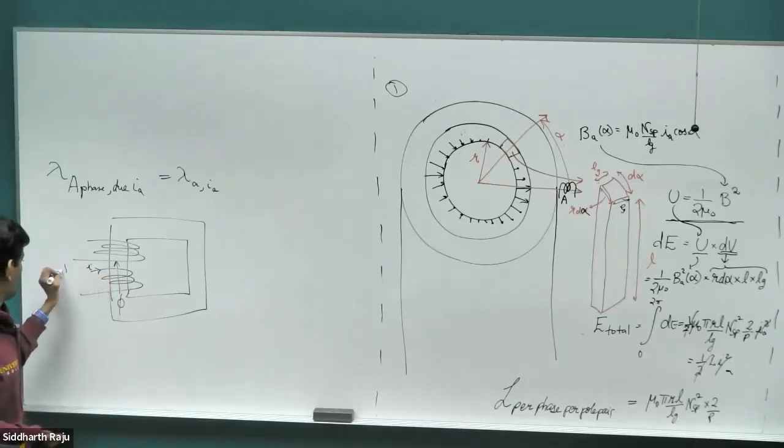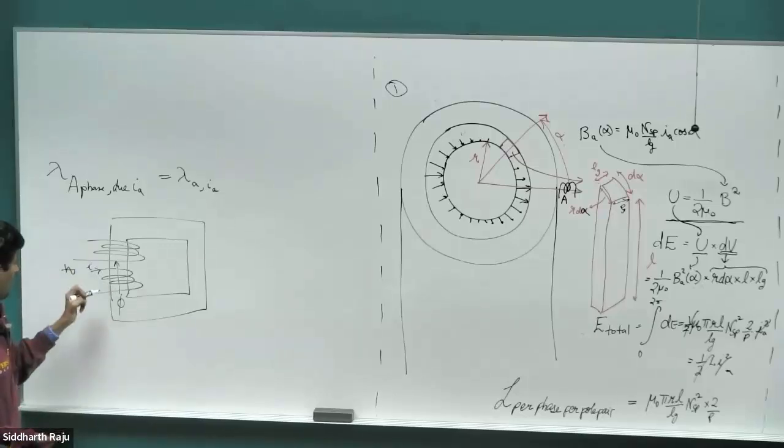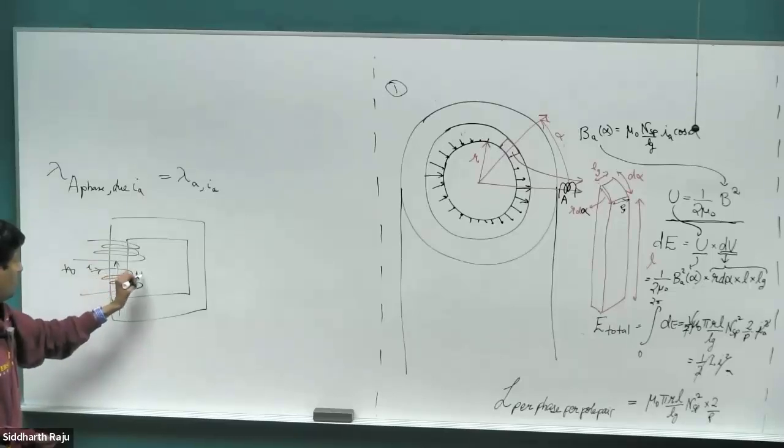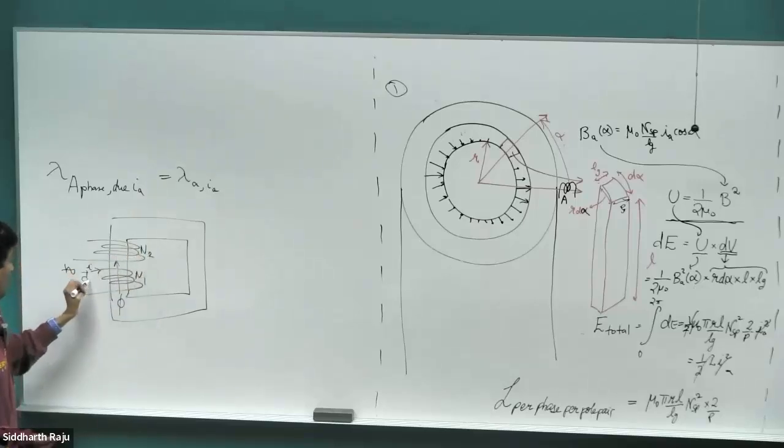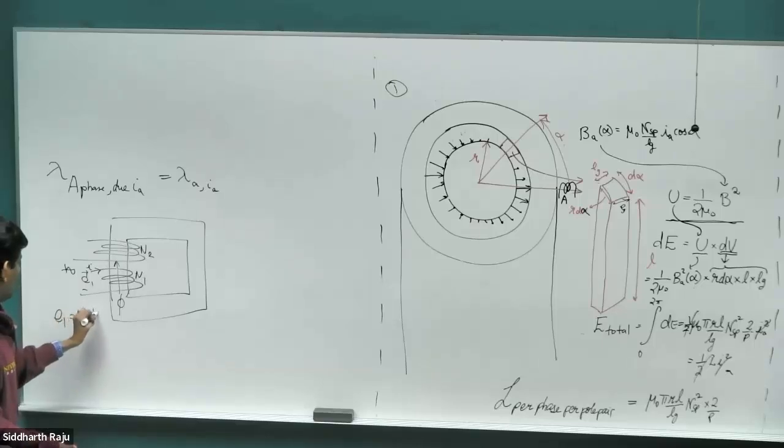I think I varied this current sinusoidally as well. Otherwise, there wouldn't be EMF in the coil. So basically, the differential of this flux, d phi by dt, times the number of turns in this coil. Let's say it's N1, N2. That is going to give me the EMF E1. So E1 is just going to be equal to N1 times d phi by dt.